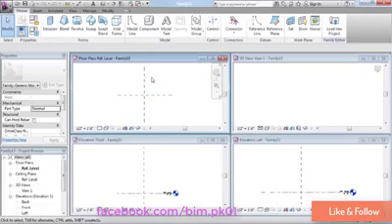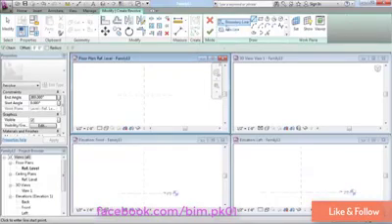Now, if I worked in plan view, then I'm going to be spinning around an axis that's going to be within the plan plane. Probably easier to just illustrate than to explain. So click on the revolve form, and you see that there are 2 buttons here, boundary line and axis line. And if you did the previous chapter, then you've already seen an example of this. We have all the same sketch tools that we had for extrusion, so these are pretty common tools.